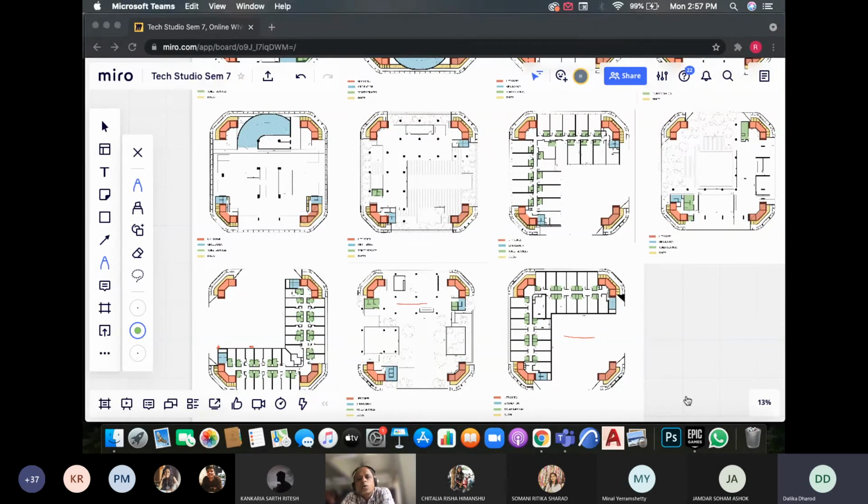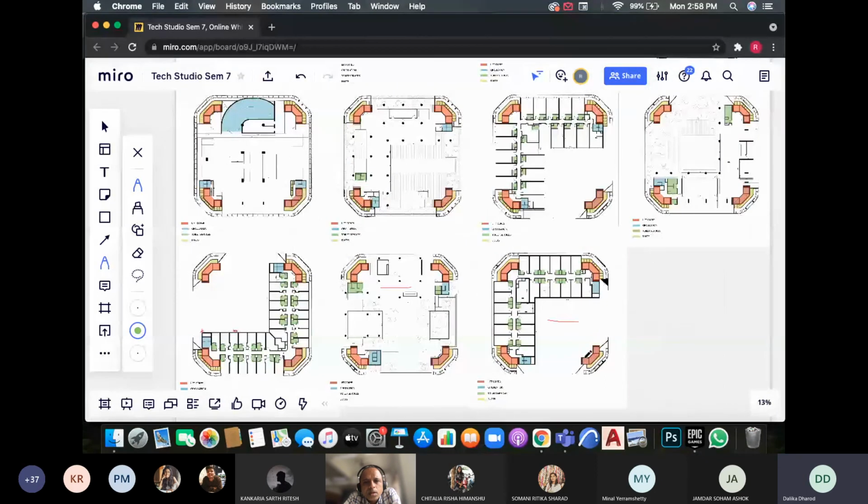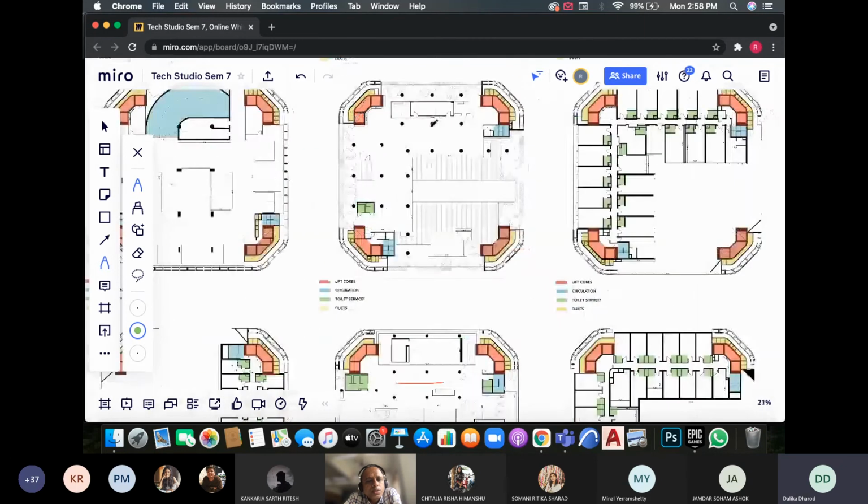So three of the corner columns are tied to each other, correct? Yes. Only one segment is not tied to the rest of it, and it is tied maybe at equal intervals. But again, that changes when you go on the top, because the L gets inverted, it doesn't continue on top of the L on the upper plan. Fair enough. But now imagine that the corners are the columns, and you are tying them together with this series. The smaller columns coming in the middle are actually supporting the slabs, nothing more than that.